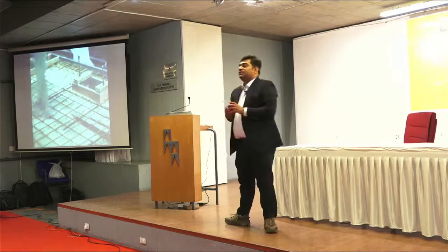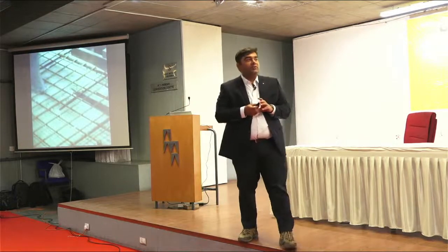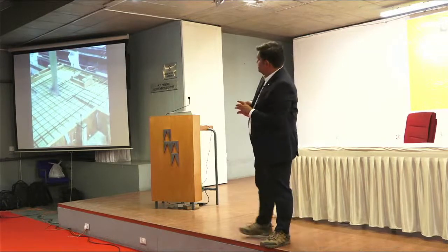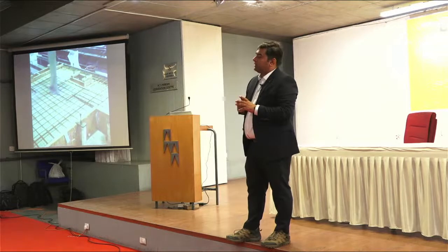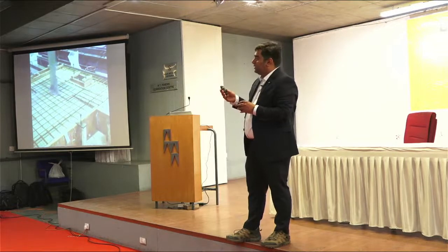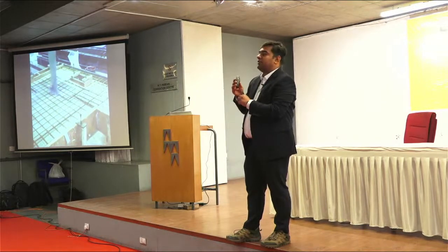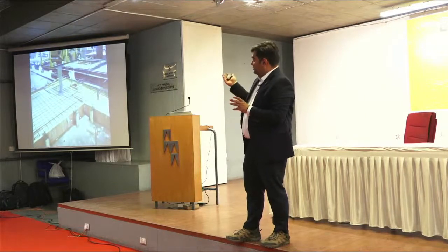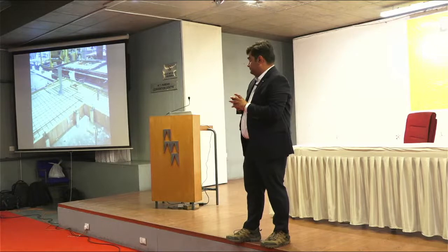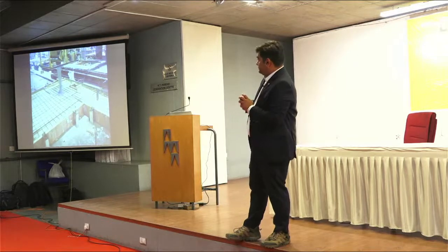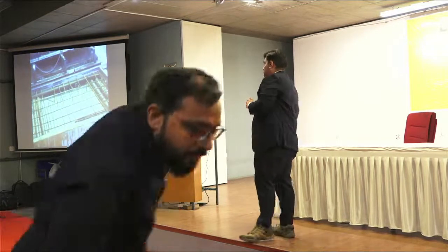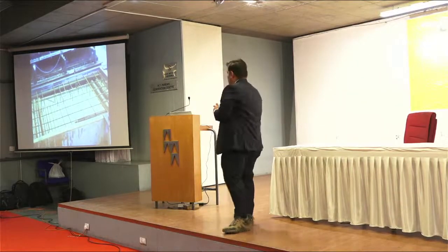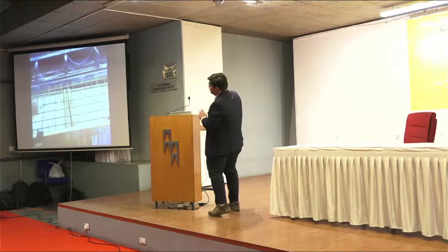The slump of this concrete is around 550 to 750 millimeters. And there were European standards for this concrete. Now India has also started developing codes for this concrete. So you can see this will be filled by itself, to every nook and corner of the form, the concrete has reached.